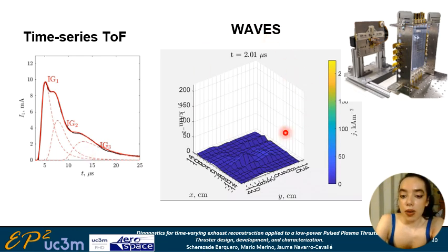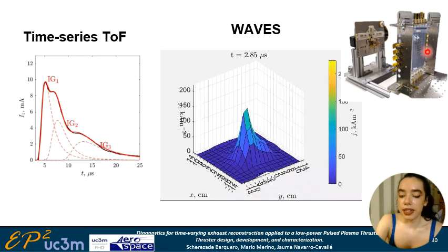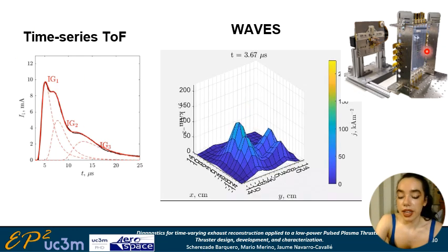So in the case of the WASP technique for the cross-section reconstruction, what we have here on the right is the probe array scan that we use to survey the plume cross section, composed of a series of wire probes that are aligned to the two cross sections, and, as with the data obtained for the previous technique, the probes are working in the ion saturation regime.